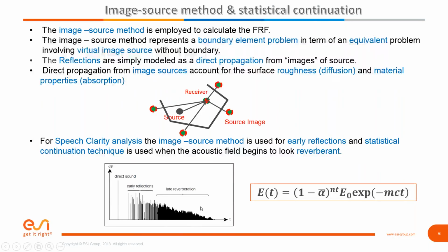And we continue to use SEA to calculate this background noise for interior spaces, form a sort of limit in time for your reverberant background noise. And at that point, you don't need to track individual rays. It becomes a lot more statistical. So we're using ray tracing, doing our bookkeeping, record keeping for direct and early reflections, SEA for late reverberation for the speech clarity, and those ratios give you your speech intelligibility or your key psychoacoustic metrics or decay metrics.